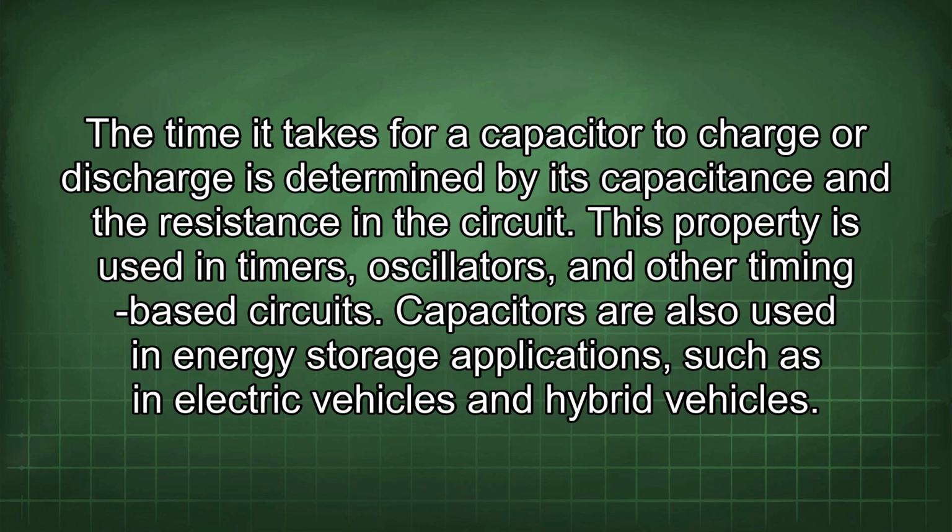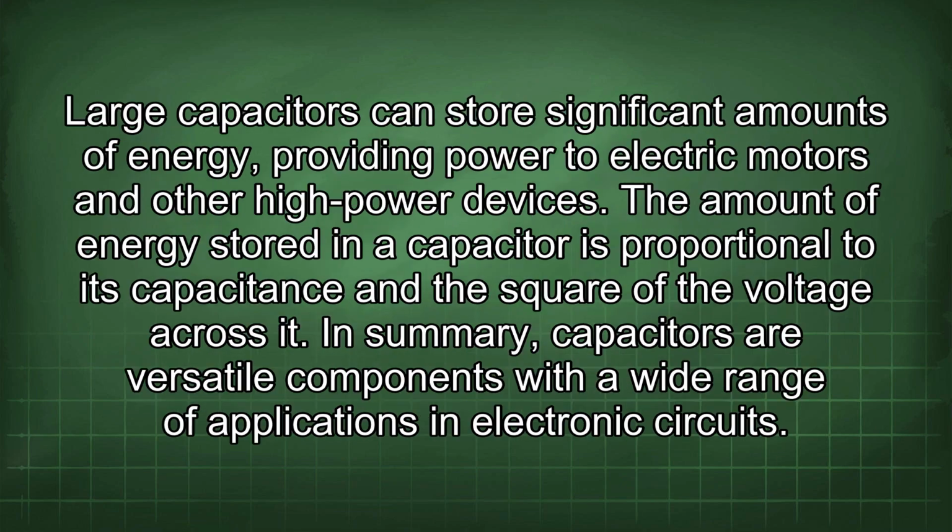This property is used in timers, oscillators, and other timing-based circuits. Capacitors are also used in energy storage applications such as in electric vehicles and hybrid vehicles. Large capacitors can store significant amounts of energy, providing power to electric motors and other high-power devices. The amount of energy stored in a capacitor is proportional to its capacitance and the square of the voltage across it. In summary, capacitors are versatile components with a wide range of applications in electronic circuits.